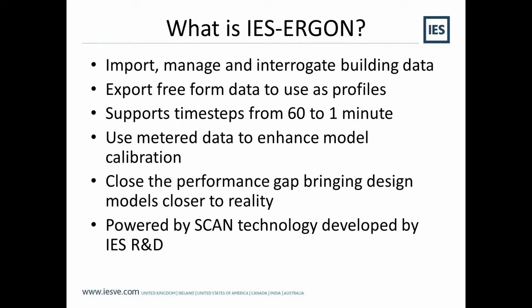The FFDs can deal with time steps from 60 minutes, 1 hour intervals, down to 1 minute if needs be. You can synchronize that with your Apache simulation time step, so maybe typically 10 minutes, maybe 6 minutes.